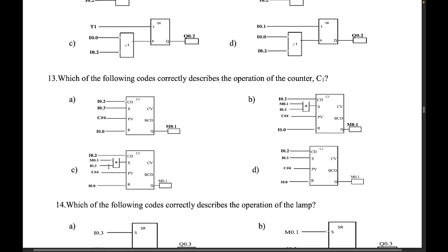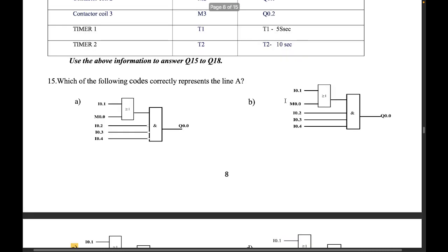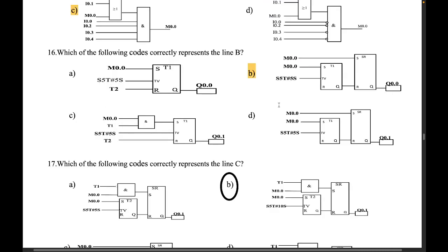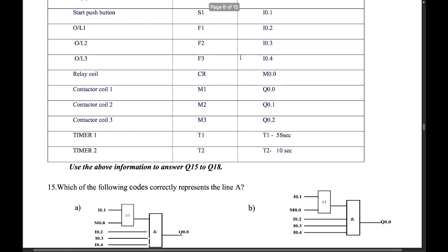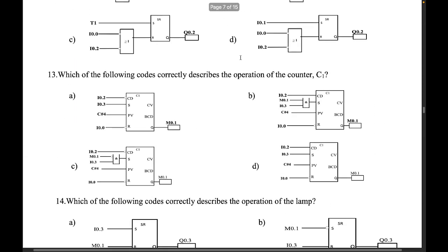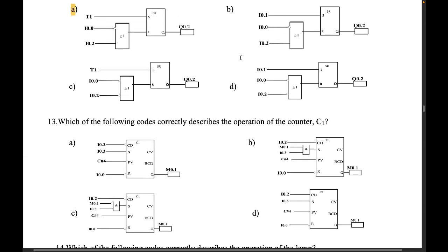The drive to the counter is the output valve, or the empty sensor, because as soon as the empty sensor senses, it closes V2, right? And then it counts 1. That's the end of the process.